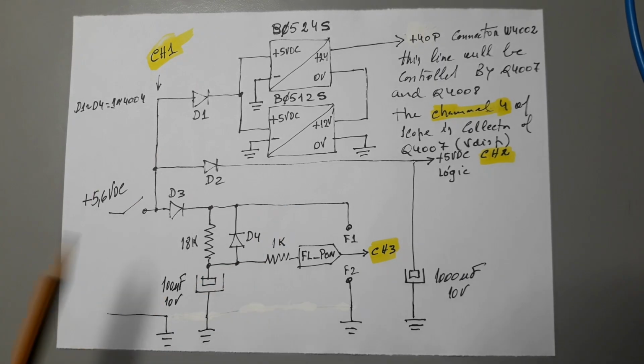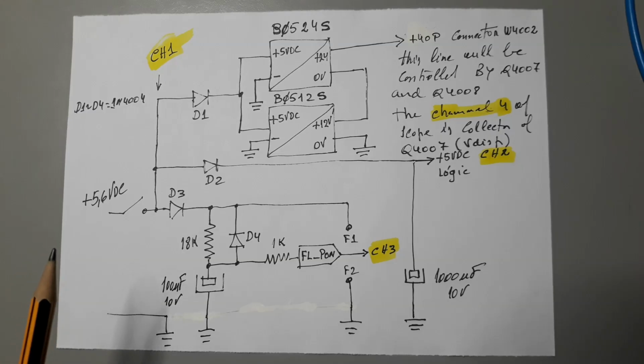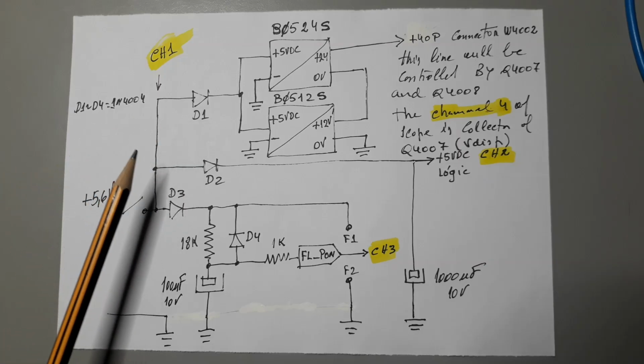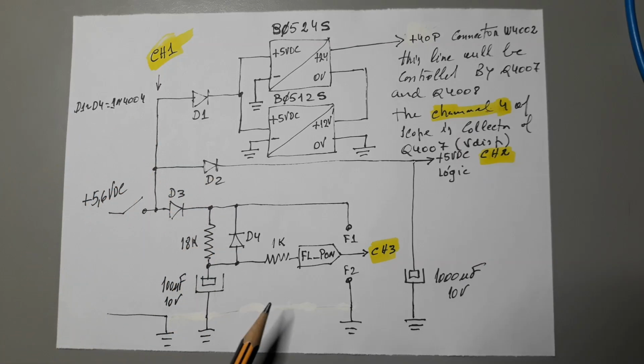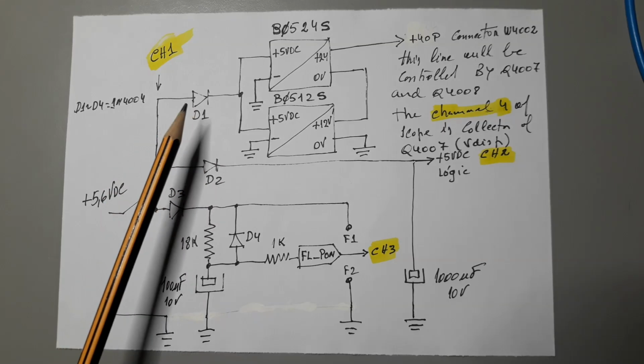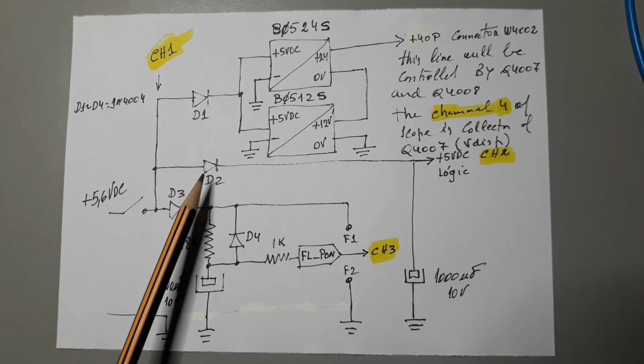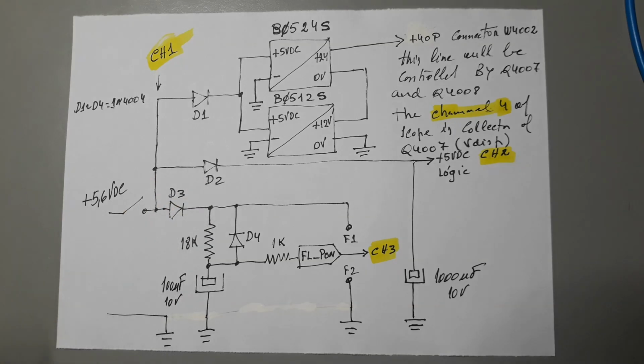This is the circuit I have made to control the presence of the voltage to the segments and grids. You can see here in each branch of the power I apply a diode. This means the voltage will drop 0.7 volts here, here also.